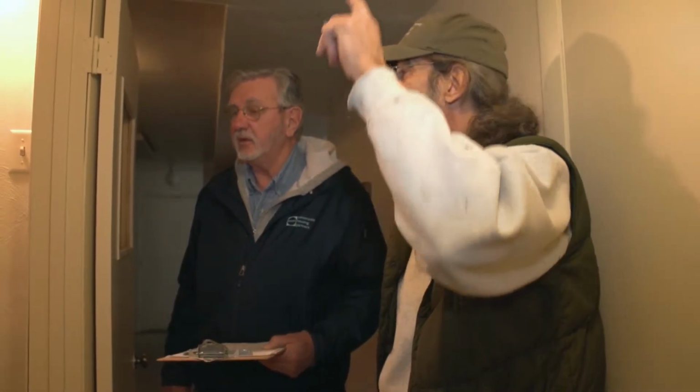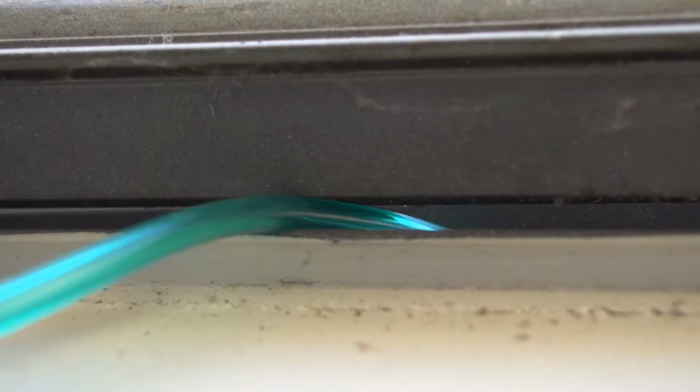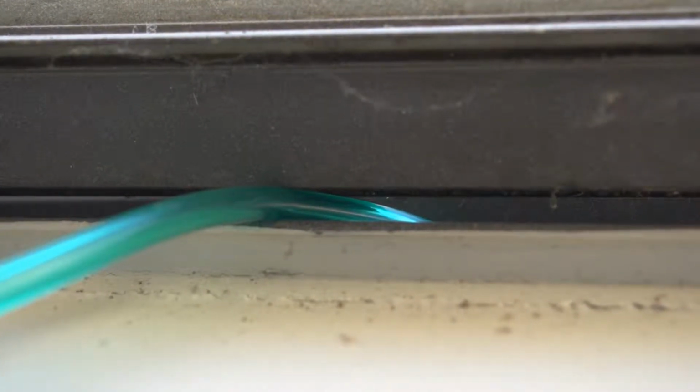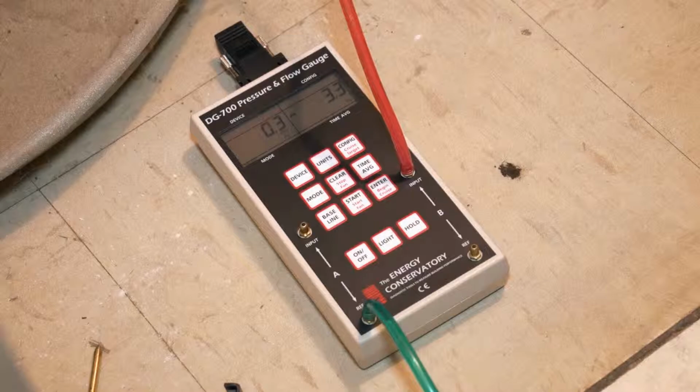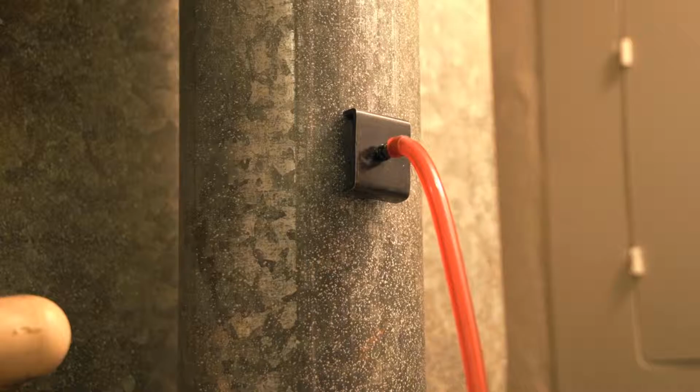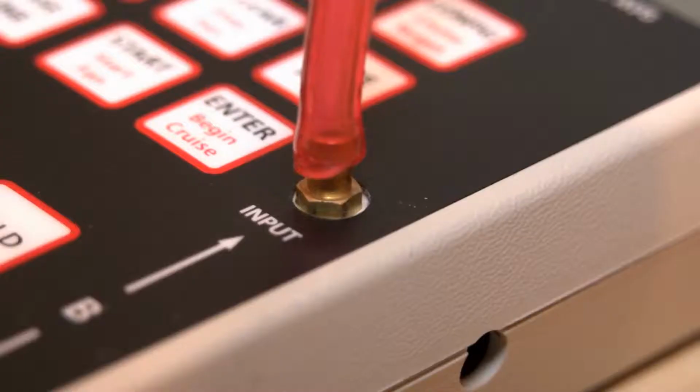At this point, if you've gathered all your materials, we can go ahead and enter the house and get started with our CAS test. We're going to run a reference hose to the outside of our CAS, actually completely out of our house, so that we can see what the pressure difference is inside our CAS as compared to what it is outside. That hose is going to be attached to your manometer on your reference side. Then we're going to make sure we have our hose for our draft gauge run from our draft gauge to the input side of our manometer.